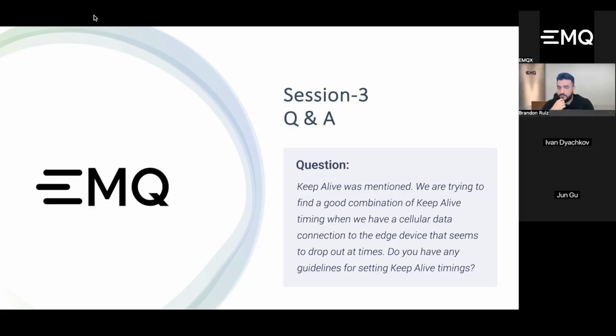No, I don't have any specific guidelines for setting keep alive timings. It depends on case by case. I would say some experimenting is required. Just maybe a too small keep alive may drain the energy, I suppose. And too large keep alive may lead to larger dropouts. Sorry, Ivan, can you read out the question? Yeah, okay, sure.